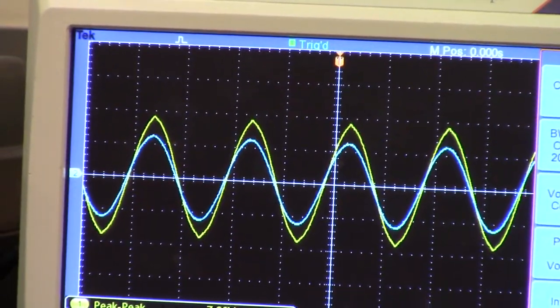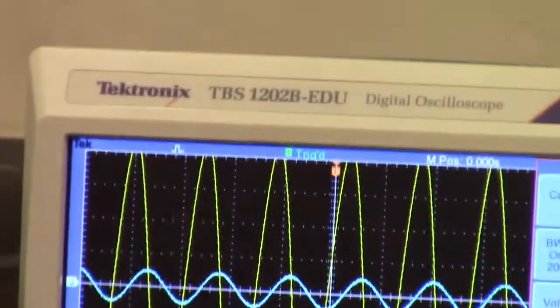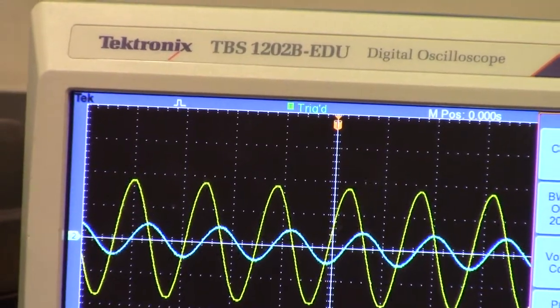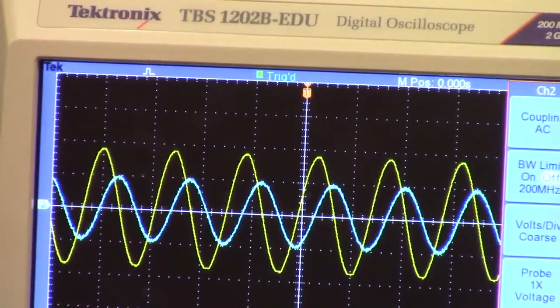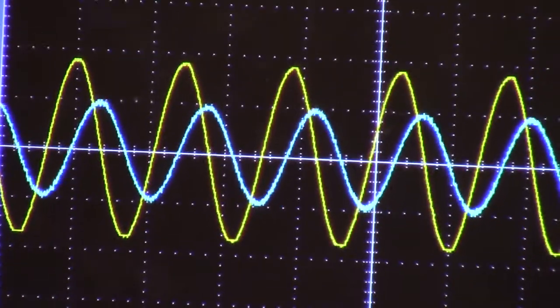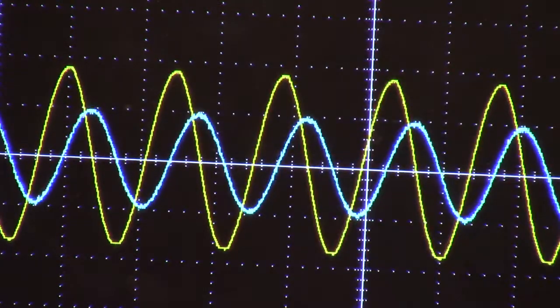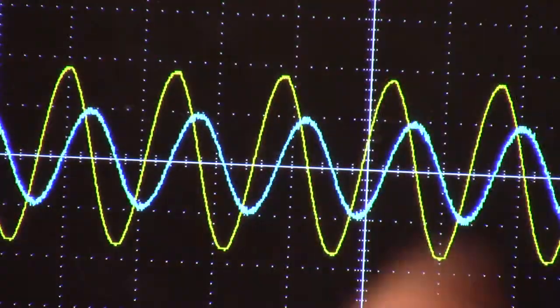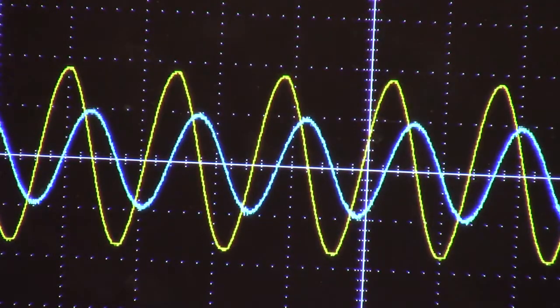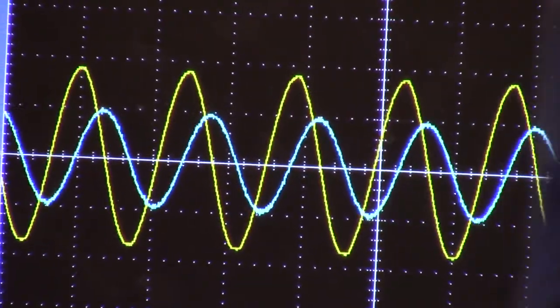But watch this. Watch what happens when I change this to a high frequency. Now maybe I'll lower channel 1 a little bit. Maybe I'll even increase channel 2 a little bit. But do you see for sure now the gold and the blue graphs here do not line up? Clearly, the peak of the gold one, which is the voltage, comes a little bit before the peak of the blue one, which is the current. Exactly. Because as we said, for these high frequencies, and so we're at about 700 right now, you are going to get this circuit to behave and act and look more like the inductor.